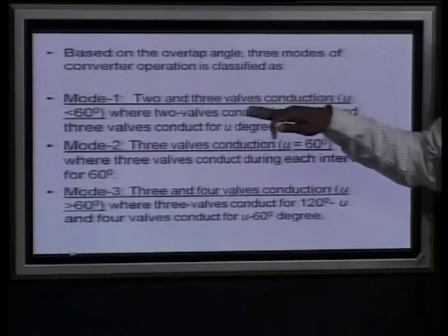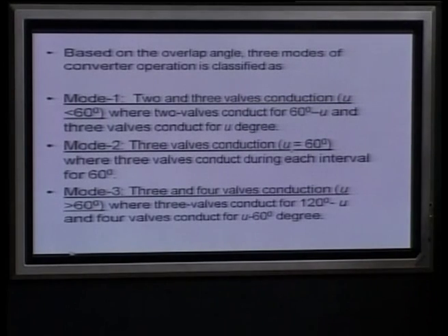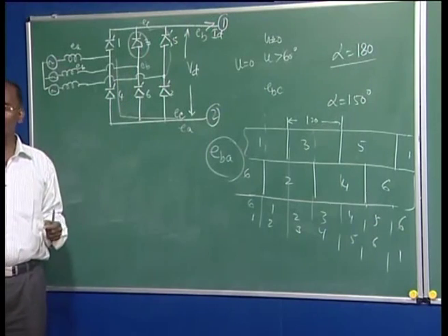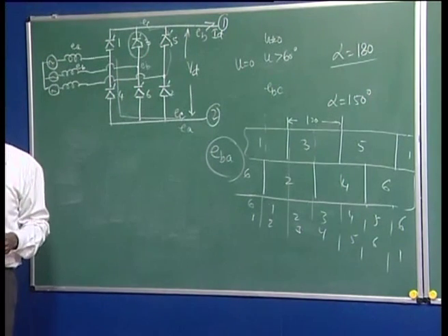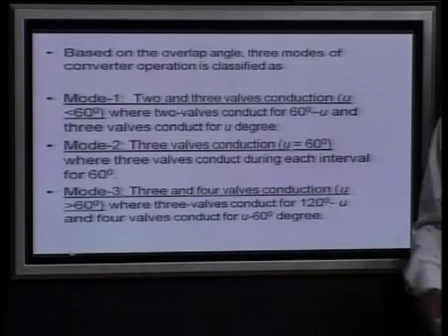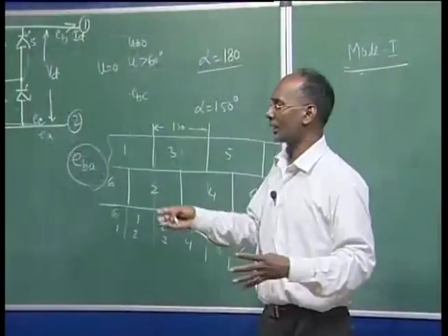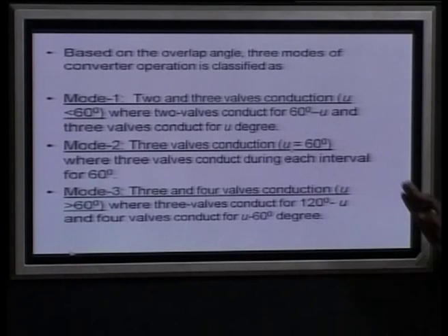No doubt this is very common, because u is not 0; it will always take time, because the current from one valve to another will take some time. It is not instantaneous. So this mode 1 is very common, but mode 2 and mode 3 are not so common. They may happen when there is some fault or problem in the AC system, that we can land up in the condition when 2 or 3 valves are conducting.